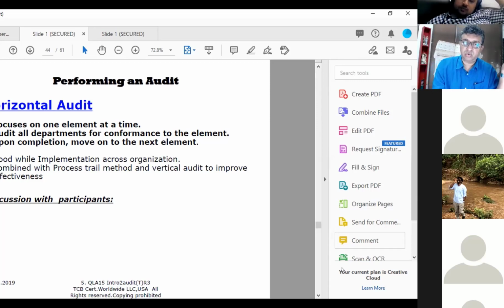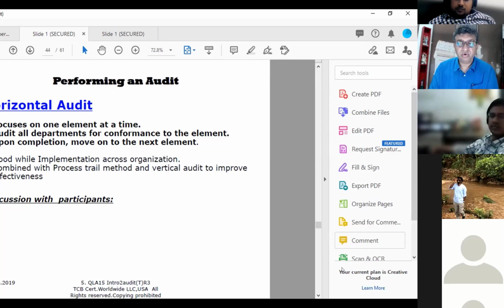So they are stored in one place, released under controlled condition to somebody who is authorized to carry it, and given back. So how do you issue the pressure gauges? How will you ensure that the gauges are kept secured, that they do not get dropped? If a pressure gauge is dropped, even within the validity period, it will become invalid. So how do you protect it?